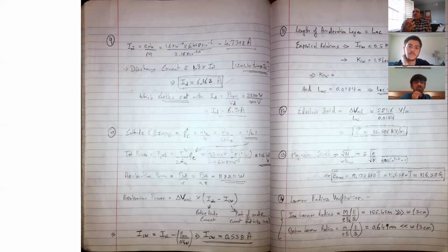So you have each atom coming out now as an ion, and it has a charge of Q of 1.6 times 10 to the minus 19. And that is the current that comes out if you divide it by the mass of each atom. Because the mass flow rate, if you divide it by the mass of each atom, it gives you the charge flow rate.